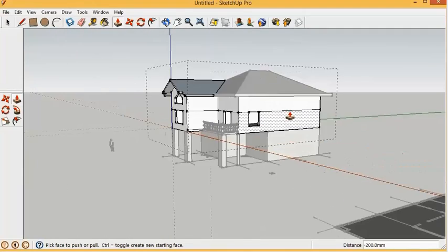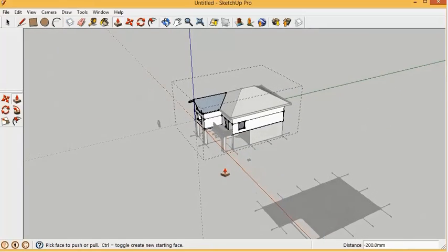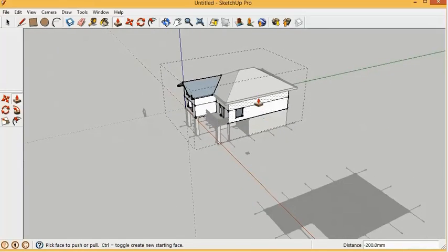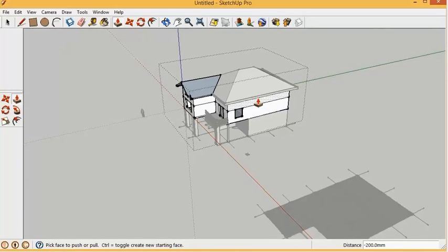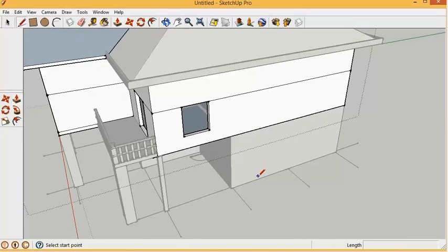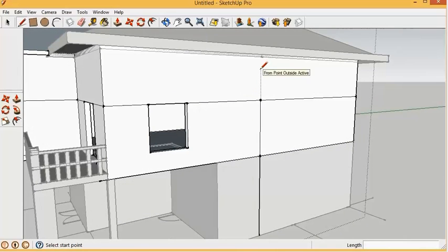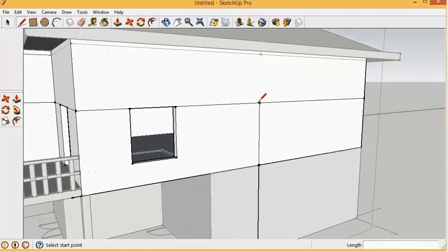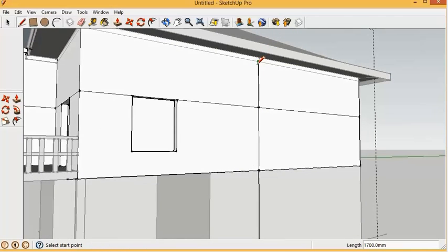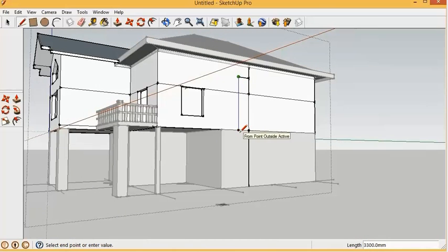Finally, another way to draw 3D objects is to draw them as text. Now we have two text tools in SketchUp. One is called text, and that's basically for labeling text. So if you want to label a drawing or something like that. We want to look at 3D text, which actually creates objects. So I'm going to select 3D text, and it brings up this window. Now into it, we can type whatever text we want. We can choose whatever font the system has and whatever alignment we want. We can also choose a height. I'm going to create, say, a 3-foot tall letter.